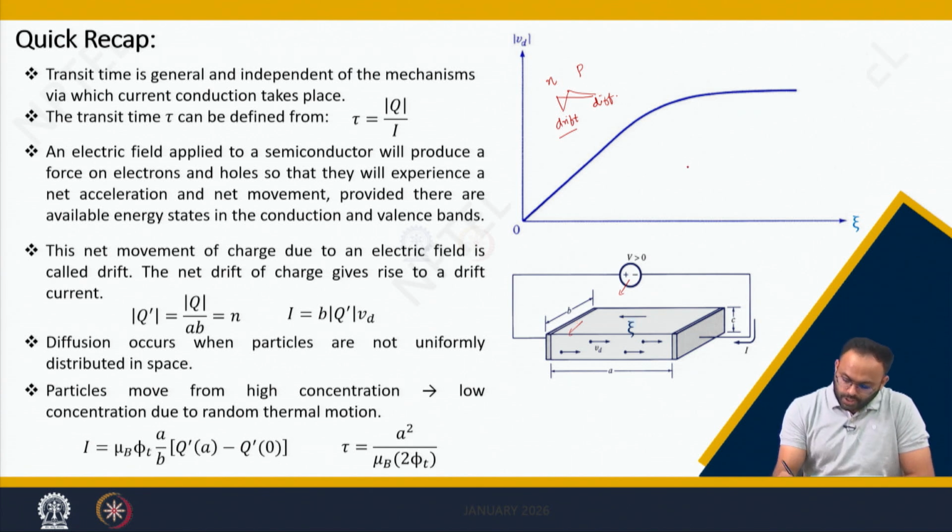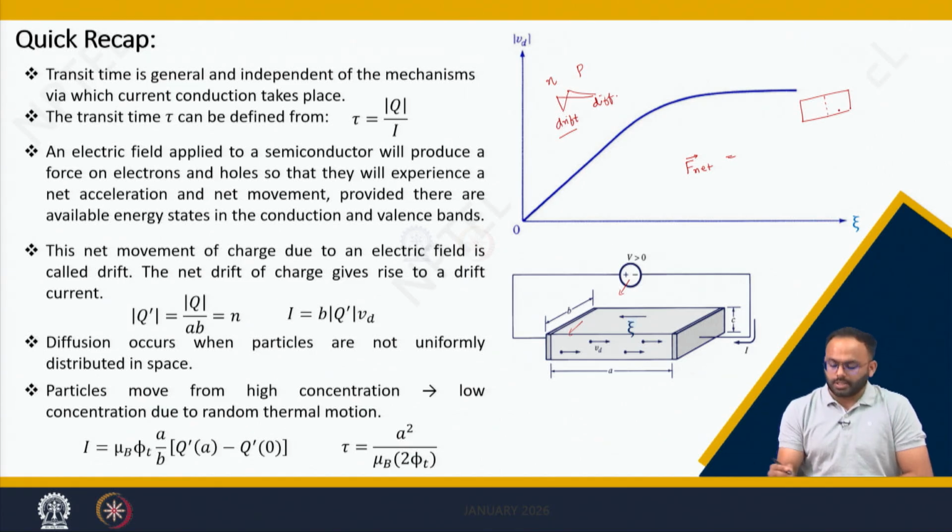We also concluded that in general drift and diffusion can be explained by a net flux which moves in the semiconductor from one position to another, either by applying voltage or due to a concentration gradient. This can be written as p times v, where p is the hole concentration and v is the velocity of the charge carrier.